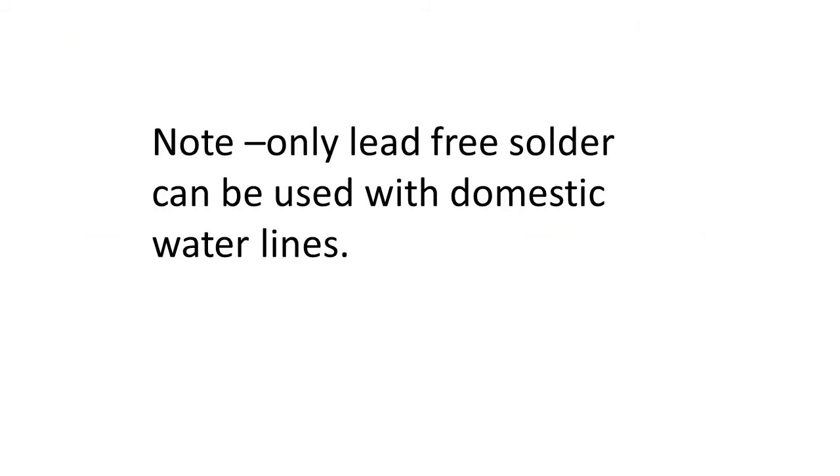One very important point: we can never use any kind of solder containing lead for domestic water lines or potable water lines. Only lead-free solder can be used in domestic water lines. Lead is very harmful to human beings and should never be used in domestic water lines.